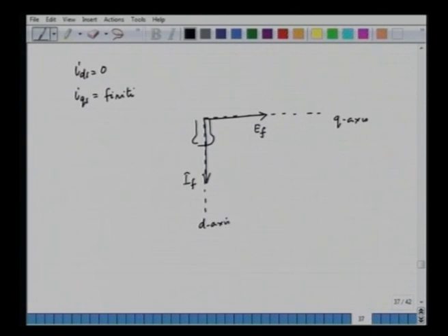IQS exists. So, for simplicity, if we ignore the resistance drop, the reactance can be added here. And what about the current? The current is along the Q axis. So, this is our IS, gamma equal to 0 here. So, the current is along the q axis. We do not have any component of Is along the d axis, and if we add this reactance here, j Is into Xs, we can assume that there is no resistance drop.